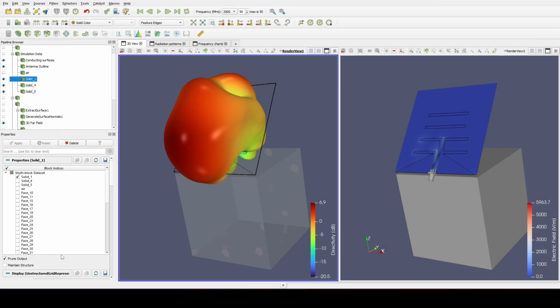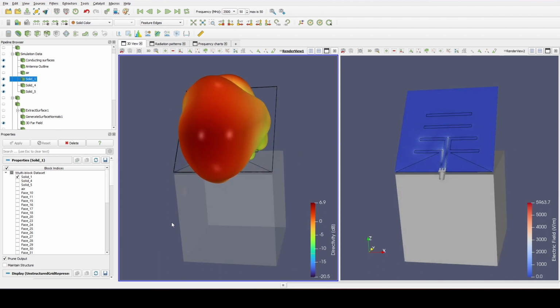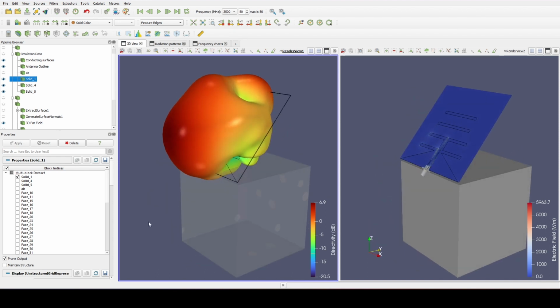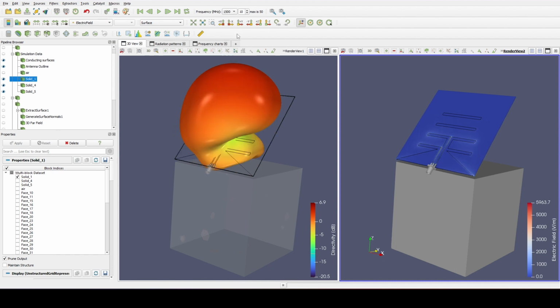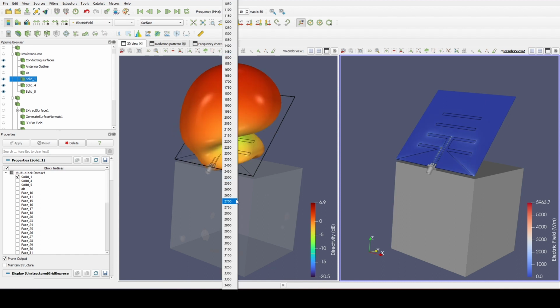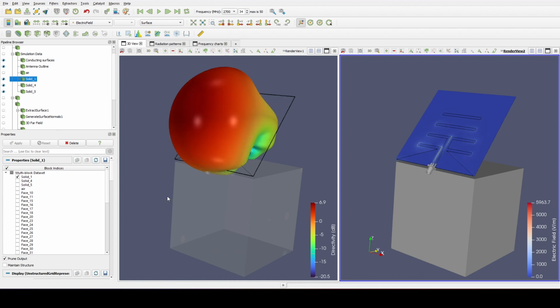And last but not least, don't forget that with CENOS Radio Frequency you can see even more information. When the simulation is finished, a preview window will also be displayed, where you will observe the 3D radiation pattern as well as the electric field distribution on the antenna. You can change between the frequencies and observe how the behavior of the antenna changes depending on the objects around it and the frequency you are working on.